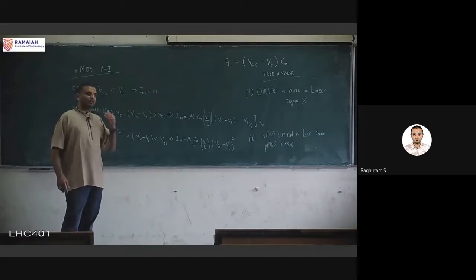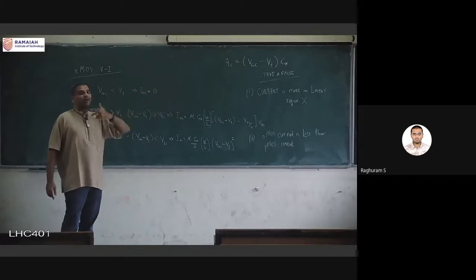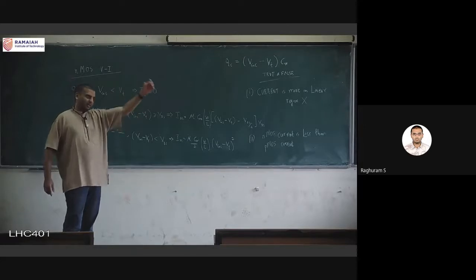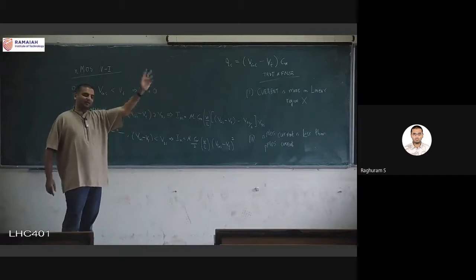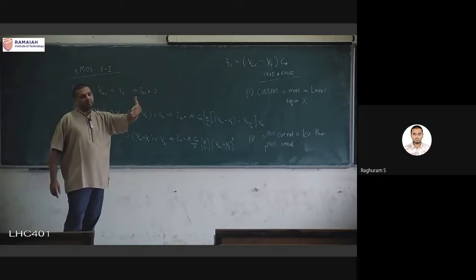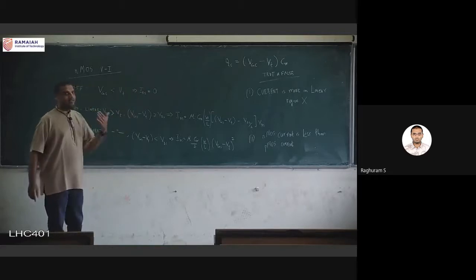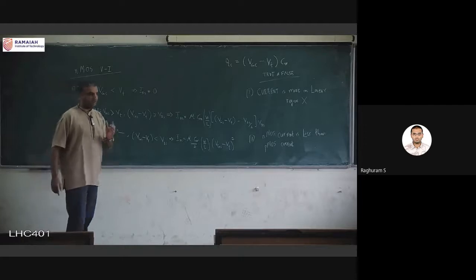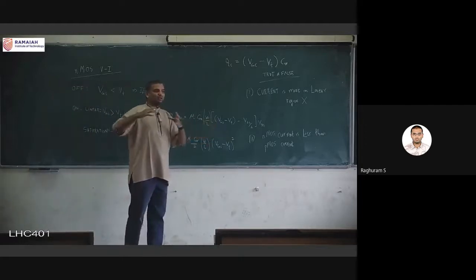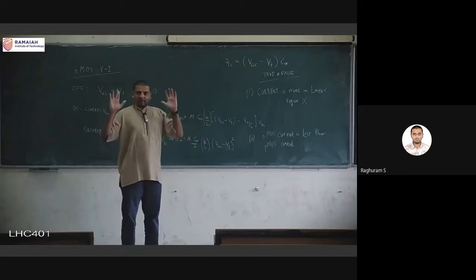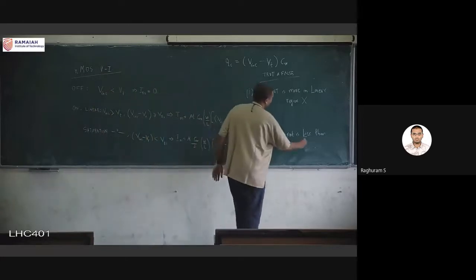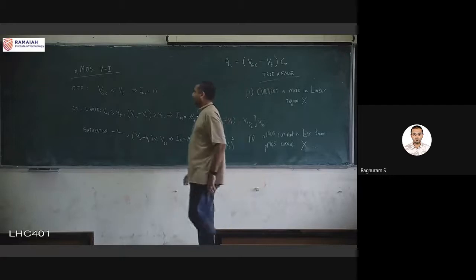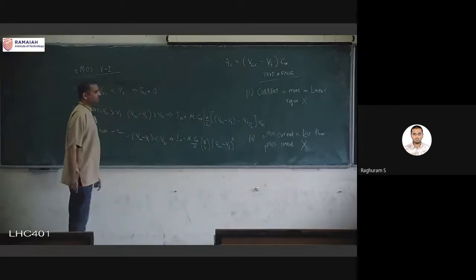But holes, the problem is every time a hole has to move, it has to break a bond. Because what is the meaning of hole? It is the absence of an electron. So if a hole has to travel, an electron has to jump from that atom into this hole. So that effectively means the hole has traveled, and if an electron has to jump, obviously the bond has to be broken. So the mobility of holes is lesser, not as good as electrons. Because of that, if all the other parameters are the same, I have two devices, NMOS and PMOS, the NMOS will be giving me a higher current. We will talk about other properties of current also as we go on.